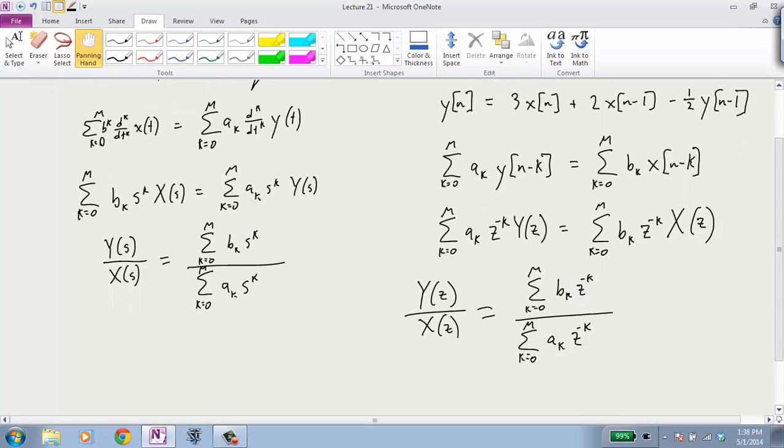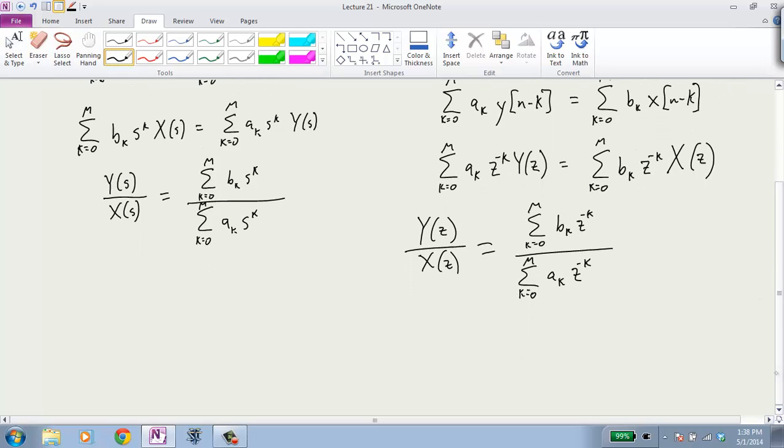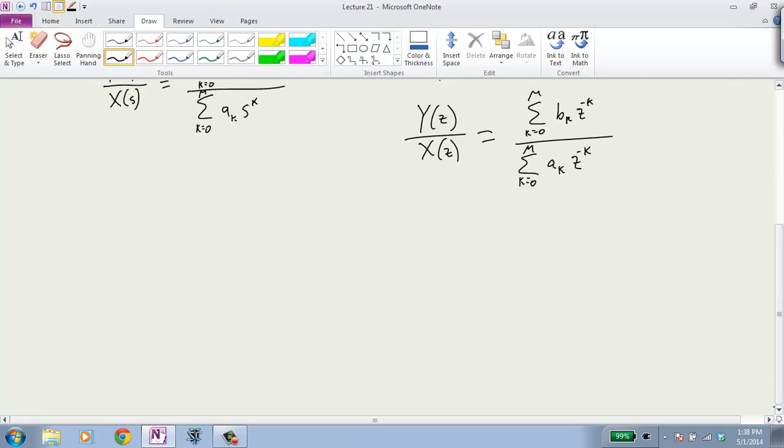And if we want to know in the time domain what the impulse response of the system is, then we have to do an inverse Laplace transform. It's a little more work. Getting the frequency domain is very straightforward, and then do a little bit more work and you get the solution in the time domain. Okay, so we had an example last time which was the following. It was just a simple one: we had a sum, we multiplied by 5, and we put it through an integrator.